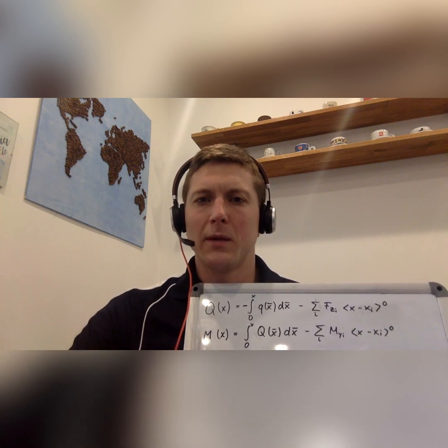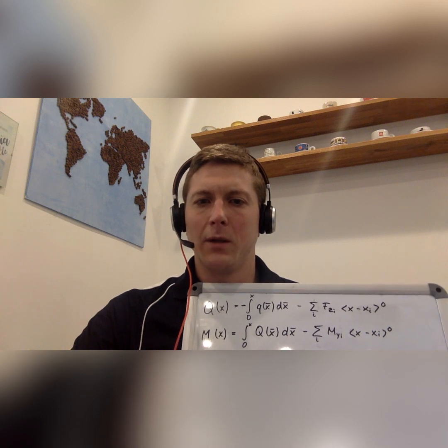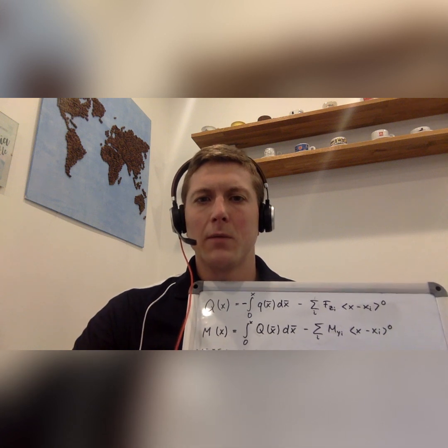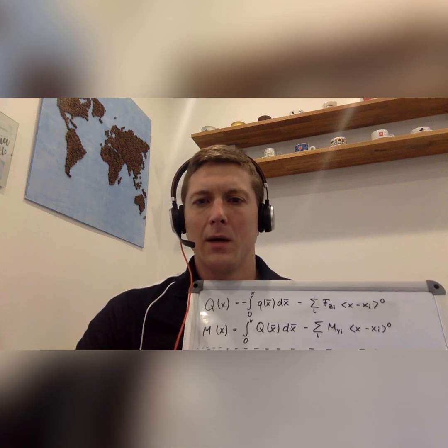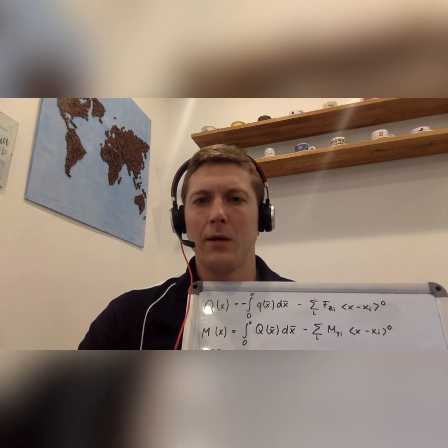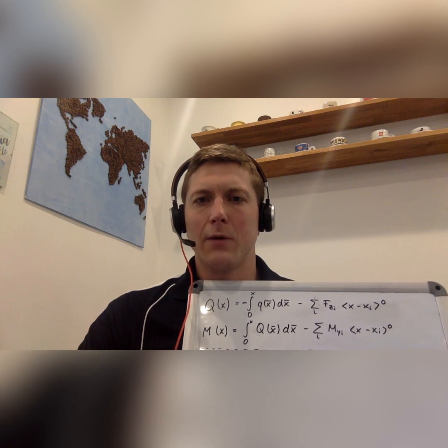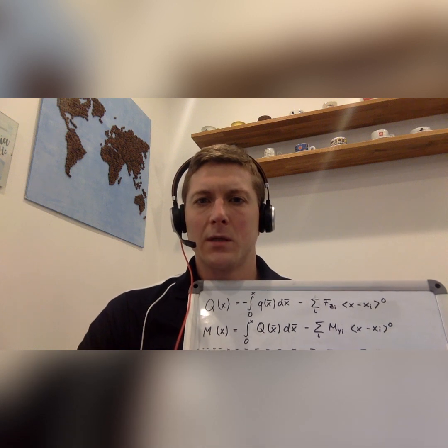For all the problems we had in the first half of our course, it was possible to determine the bearing reactions out of the equilibrium on our beam before making any integration. And keep in mind what we did all the way: if we had a line load, we substituted this line load by the resulting force, meaning the integral over the complete line load. So the area which is covered by the line load is identical to the amount of the equivalent force, and the line of action of that force crosses the centroid of the area which is covered by the line load.